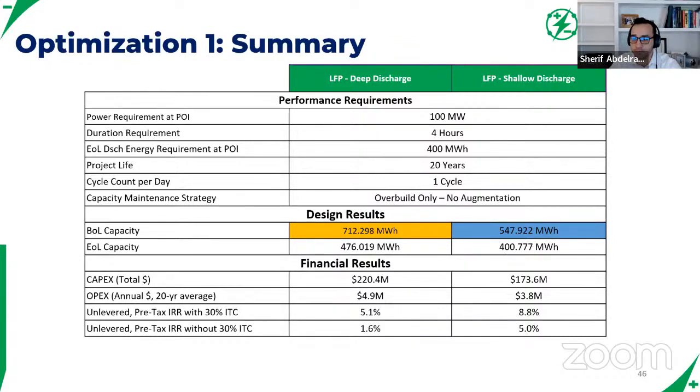When we say lithium round trip efficiency is 85%, that's a really, really general statement. It could be much, much worse if you're just keeping the battery there and not cycling it. So it's important, if you're interested in a comparison between two different technologies like lithium and flow, to model both and see for your specific use case which one makes sense.